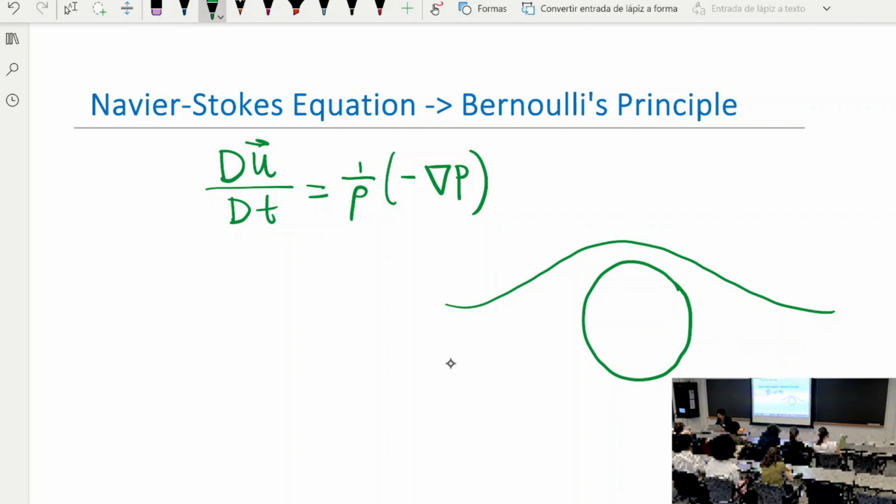Let's imagine we have exactly our previous case. This is a steady state flow, meaning if I fix my eye at one particular point and don't allow it to go with the streamline, the velocity over there is going to be constant. Here there is a significant difference if you follow the streamline: at t equal to 0, you're looking over here, but at t equal to, let's say, dt, you're looking over here, right? So if you follow the streamline, then the flow particle is actually changing in speed. But if you fix your eye either at the first point or the second point, then the speed is going to be constant.